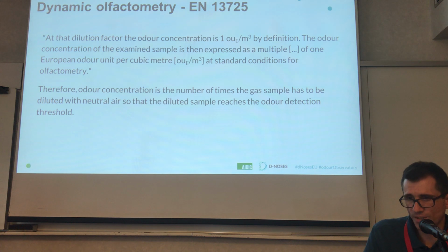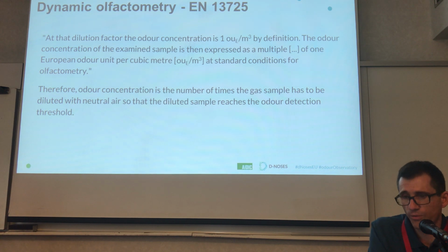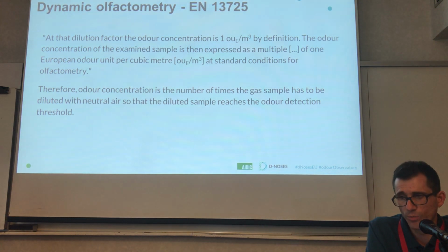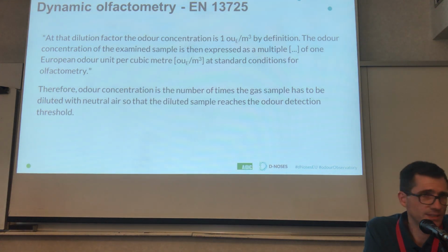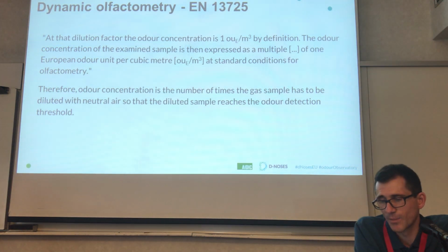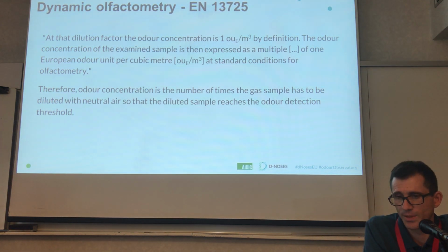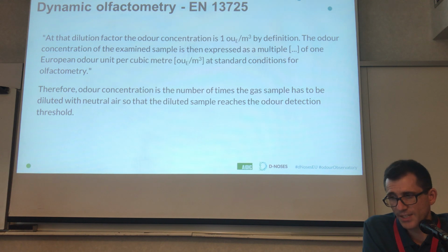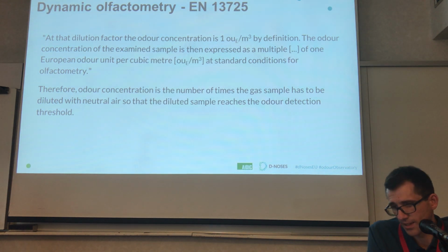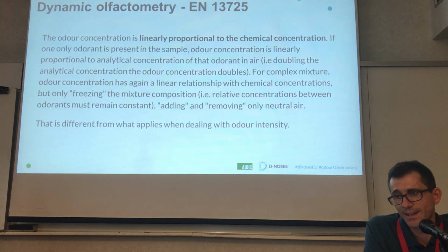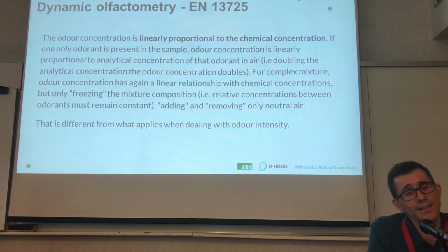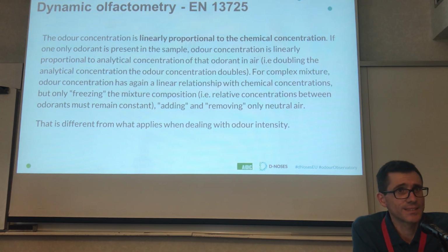The odor concentration of the examined sample is then expressed as a multiple of 1 European odor unit per cubic meter at standard conditions for olfactometry. So the odor concentration is, as Laura said, the number of times the gas sample has to be diluted with neutral air, so that the diluted sample reaches the odor detection threshold. So there is, in fact, a linear relationship between the chemical concentration of the gas and the odor concentration.